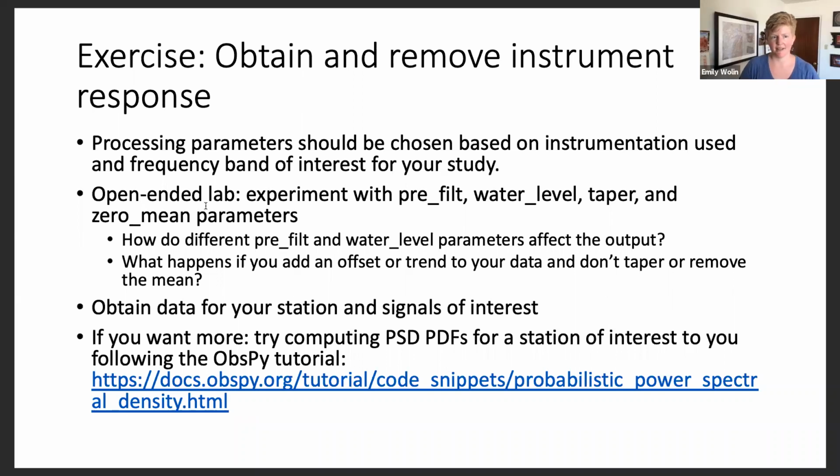Okay, let's see here. I will say in principle, no, right? If you have the same seismometer, let's say an STS2 broadband seismometer, recording at 50 Hertz and you downsample it to 5 Hertz versus just recording at 5 Hertz initially, if you are close to the Nyquist frequency, 2.5 Hertz, and about 50% of that, it'll be different, right? Because that decimation process and the anti-aliasing filters that you're using will make a difference. At long periods, in principle, no.